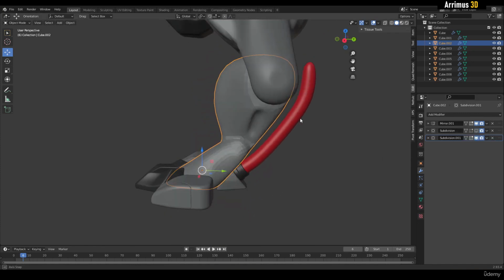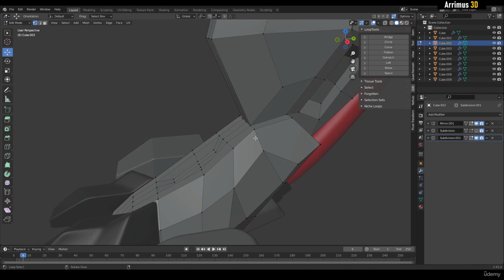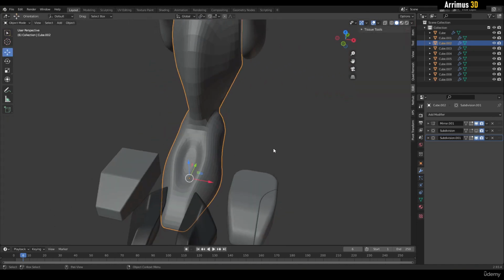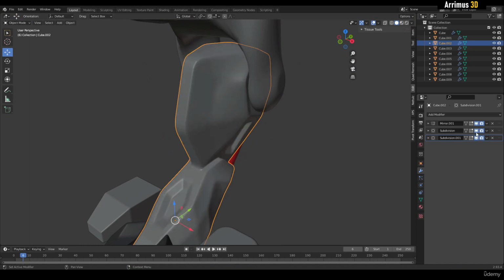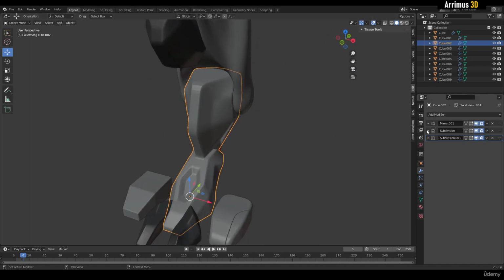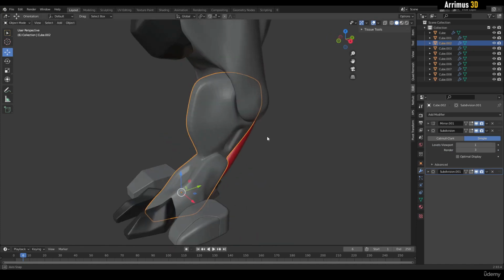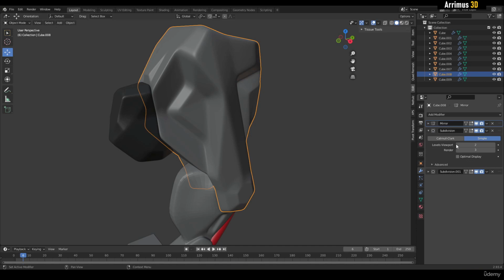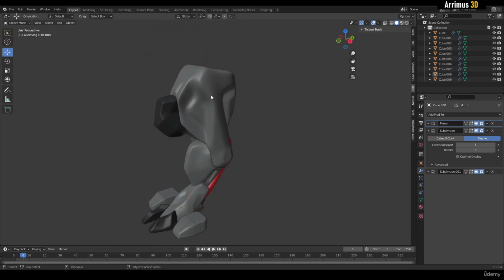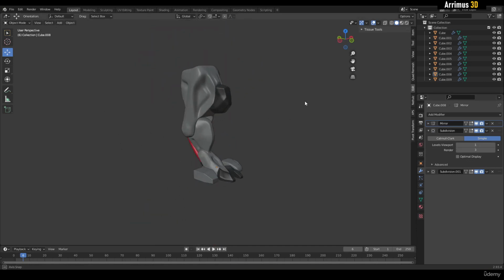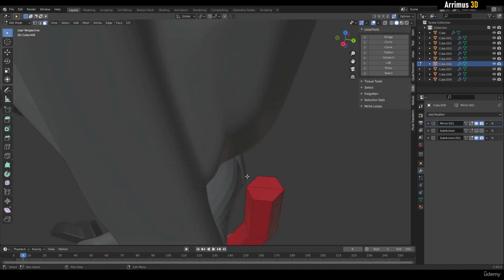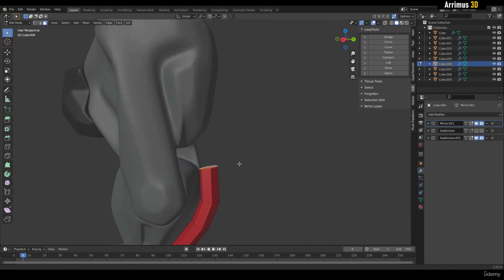And now you can do a different workflow where you start using loops, for example, and just start getting more crazy organic shapes. What you can also do is, if this is too angular, you can simply go in here and change this to 1, for example, and that will smooth things out as well. So we're going to activate that, but we're going to change that to 1 just to smoothen things out right here. All right, let me just expand this wire a little bit here.